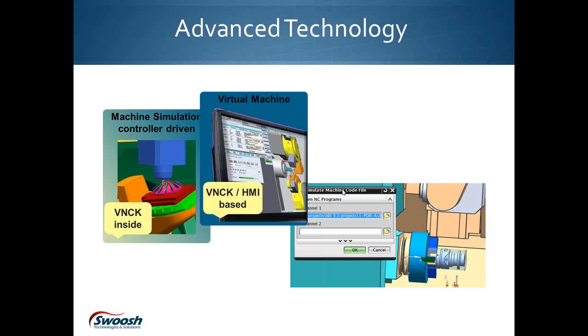And it also has something fancy for Sinumerik controllers that's called VNCK. So what you have for your Sinumerik controllers is you can actually emulate the actual hardware that's out on the floor. So it's exactly like having access to your machine control, but it's a little box that plugs into your machine, and it's a virtual controller. So it'll act exactly like your machine would on the floor.